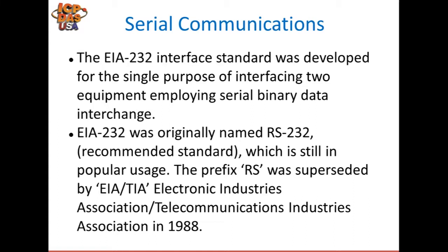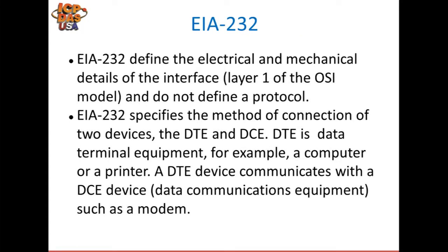It should be emphasized that RS-232 and other related EIA standards define the electrical and mechanical details of the interface, layer 1 of the OSI model, and do not define a protocol.